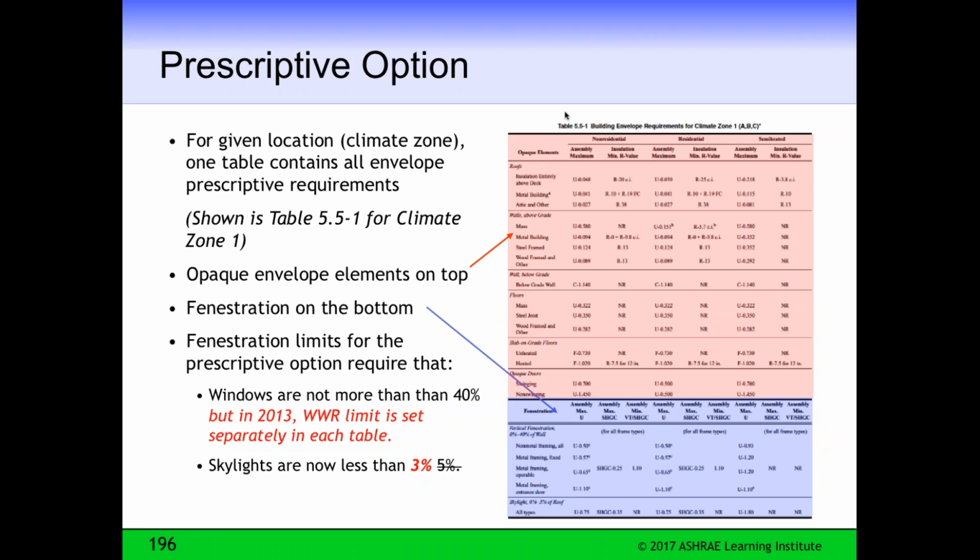This presents challenges for compliance because you must use the whole building approach, either an ECB or Appendix G, and your baseline building that you're complying against is going to have 40% glass, or if you're using Appendix G in 2016, depending on your building type, it could be 32% glass or 25% glass or even less than 20% glass as a baseline. So the amount of glass can impact 10 to 20% of the total building energy difference. So it's a really important factor.